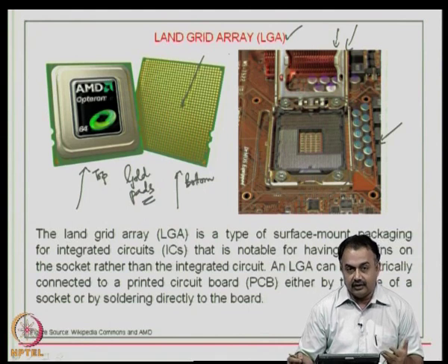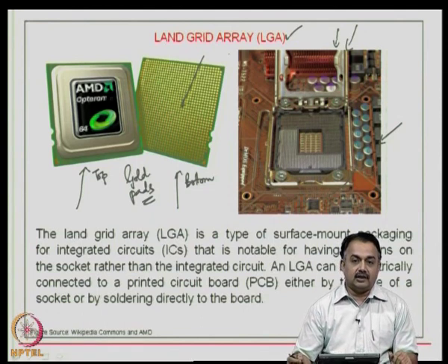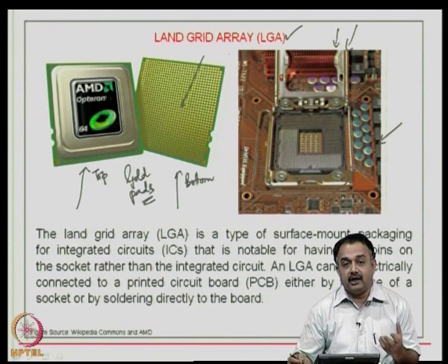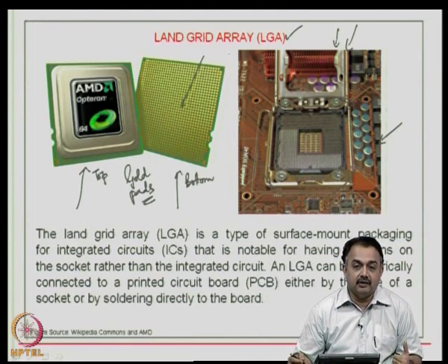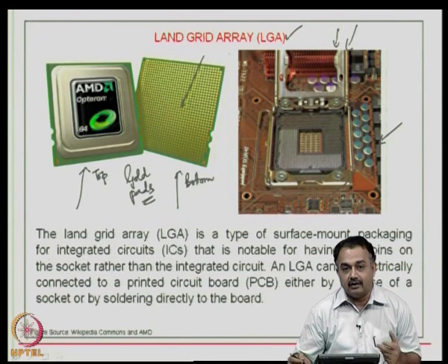But the data sheet also says that you can solder it directly onto the printed wiring board, but as you know, this is a very expensive package. It could be possible that you have to repair and rework on this active device because of failures that could be expected. Therefore, it is easy to use a socket and do repair and rework or change the processor rather